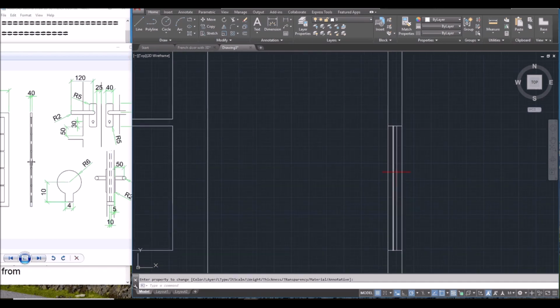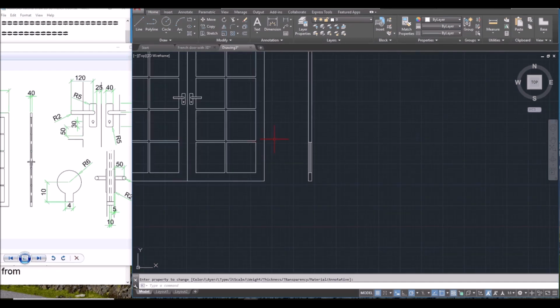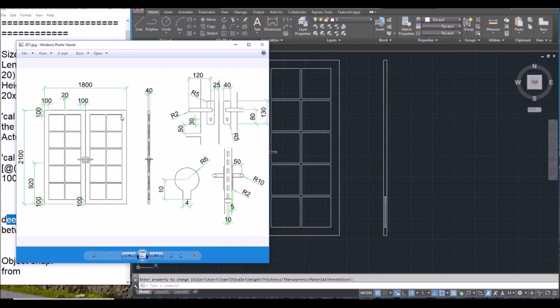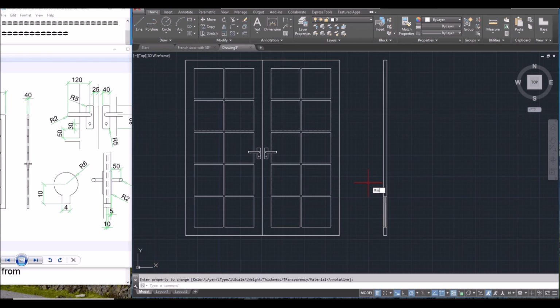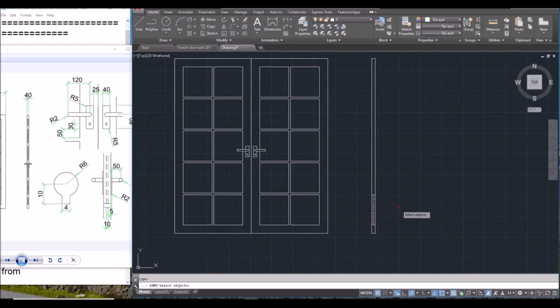Okay, but I can't see the hidden lines because you have to set up the line type scale to make it larger. If I put 1 to 50, I can put everything inside A3 size paper. LT scale, spacebar, 50, spacebar. Okay, so 1 to 50, it looks like that. Now I will copy the whole thing, spacebar.